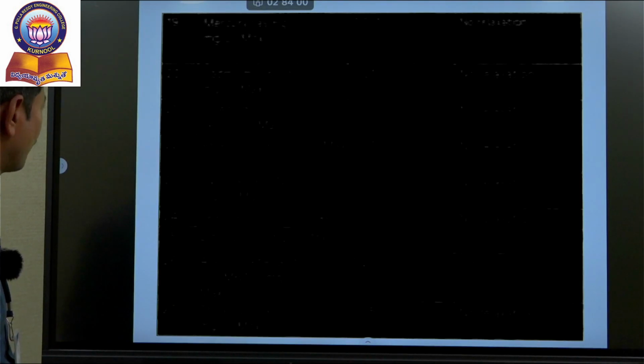Selenium 0.01, arsenic 0.01, cyanide 0.05, lead 0.05, zinc 5 is good, and detergent 0.02 is good. Chromium below 0.05 is good, and mineral oils 0.01. Pesticides should be 0, and radioactive materials are not allowed. Alkalinity 200 is good, allowed up to 600. Aluminium 0.03 is good, and 0.2 is allowed.